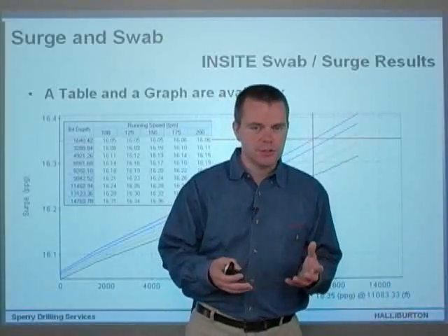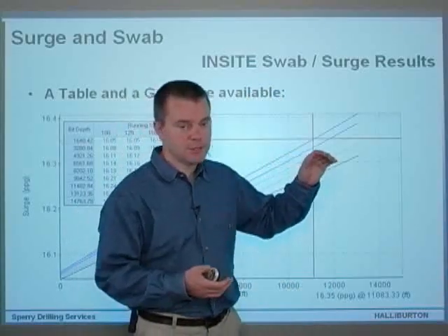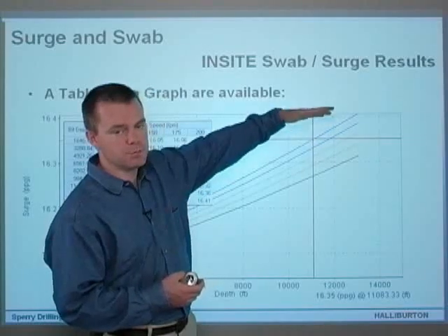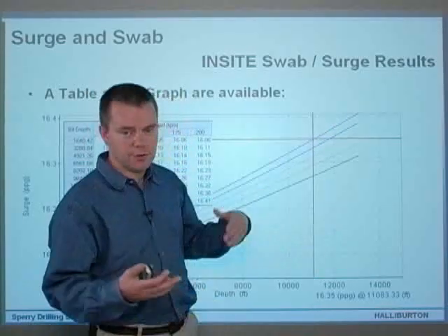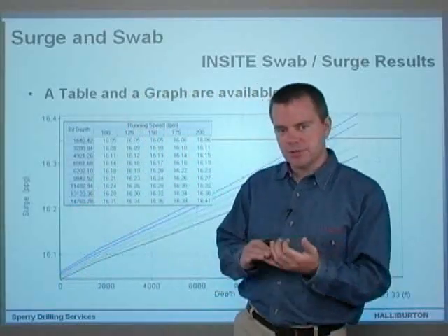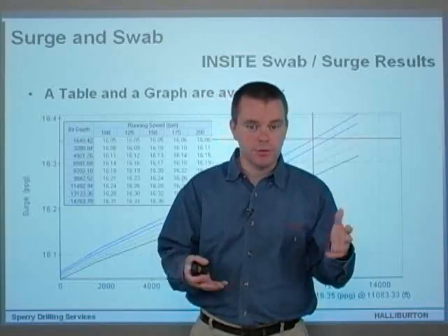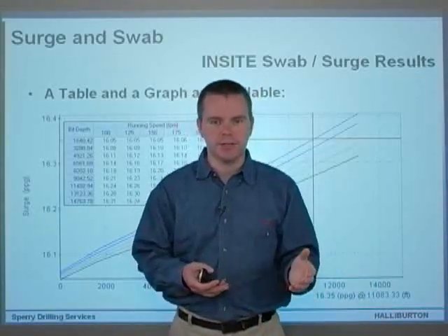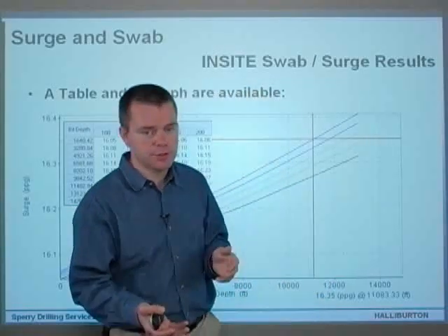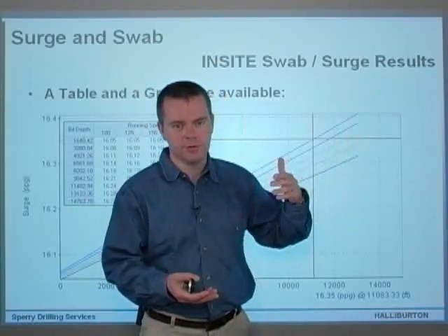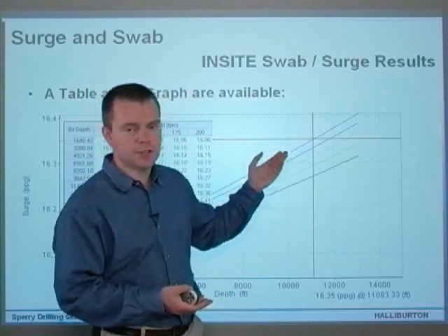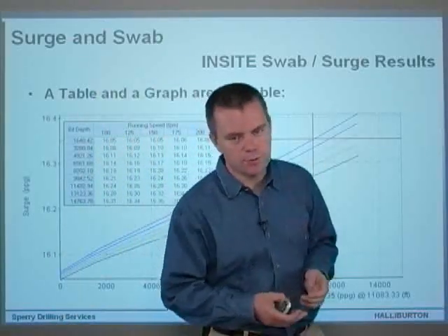Right, although I've just mentioned the constraining factors as being the fracture gradient maybe as your upper constraining factor for surge pressure and your pore pressure for swab pressure, sometimes using fracture gradient and pore pressure will give you the ability to just run the pipe in as fast as you like, because you're not going to swab something in from normal pore pressure in general, and you're not going to fracture rock that's very, very strong. So sometimes the calculation will just say you can run in as fast as you like, especially in things like 17.5-inch hole and so on.